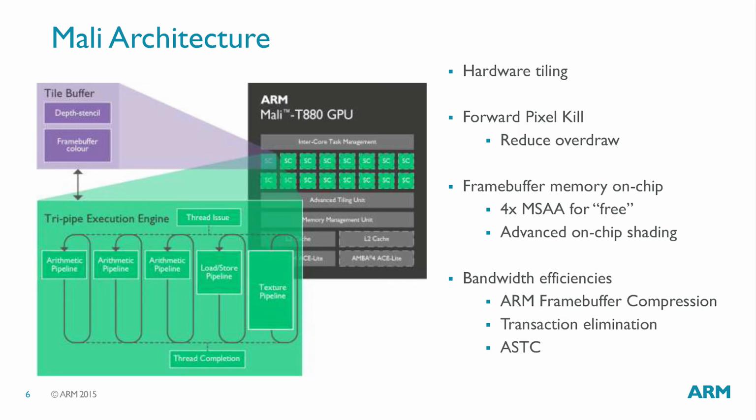There's frame buffer compression, or AFBC, as it gets abbreviated to, which basically means anytime we write the fragments out from the chip, they get compressed before they even get losslessly compressed across the memory bus. They're not then editable, but for render targets and things, this is all fine. This just happens magically. There's a thing called transaction elimination, which is really useful for UIs. And it works surprisingly well in games as well, which is a bit scary.